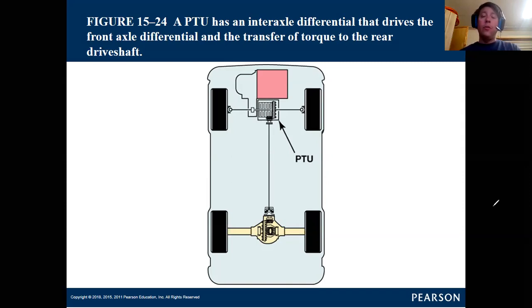The front axle has the ability to put out equal power between each front wheel. The rear axle has the same ability to put out equal power from each right and left rear wheel. Now, front to back is where we get a slight variation from make and model. Some manufacturers do a really good job of splitting power between the front and the back to like 50%. Some manufacturers can only give maybe the rear 60% and the front 40%.